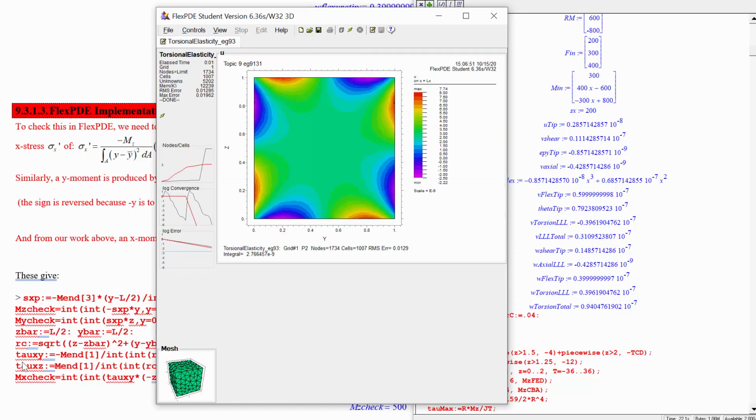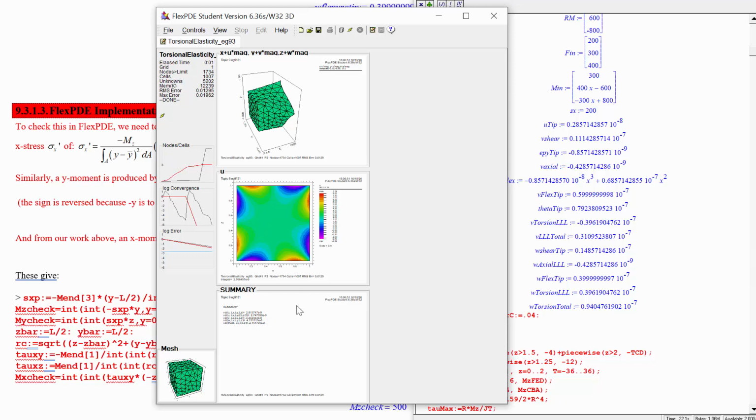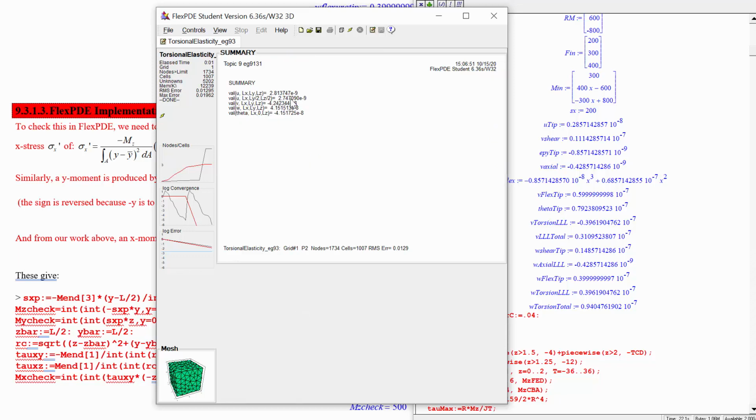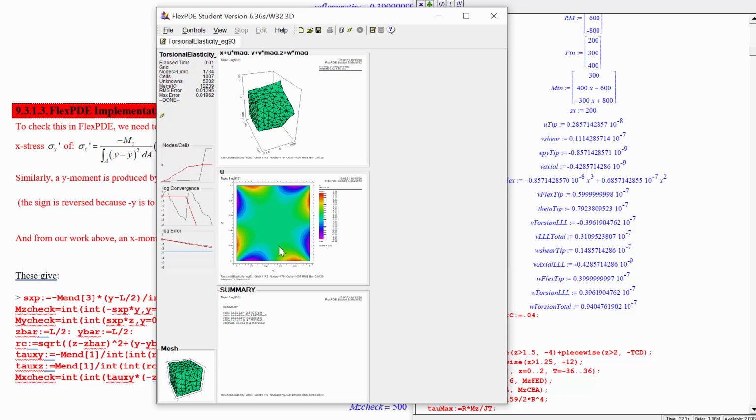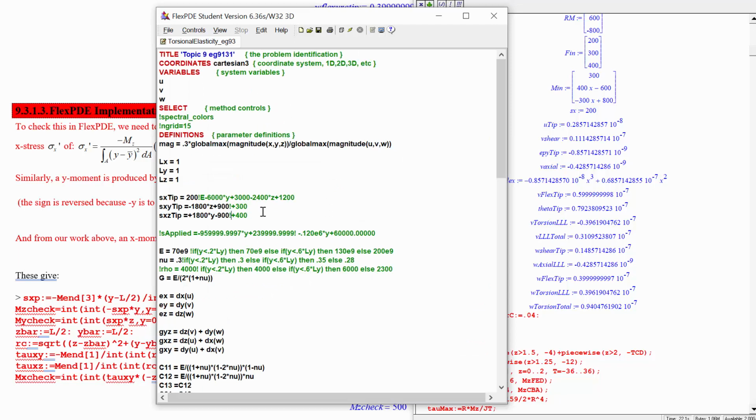So it's some kind of a combination effect of those different factors. We now have a U displacement at the center that mostly matches the top. When we got rid of the shear that was showing up, with the twisting, the shear ends up making a big difference to those x displacements.